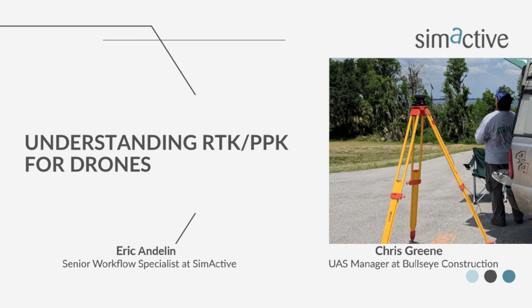So Chris, having that background, can you fill us in a little bit on your end, what the two are? I guess I'll start with the RTK. This is when you're getting corrections in real time from the drone to a base station, whether it be an on-site base station or a state base station, which is what I use mostly. The North Carolina network has a pretty robust network, so I'm not overly confident in it, but I use it, and I've gotten decent results.